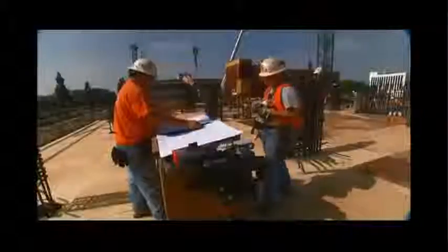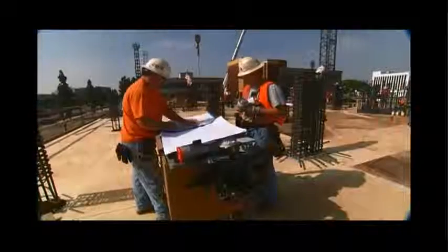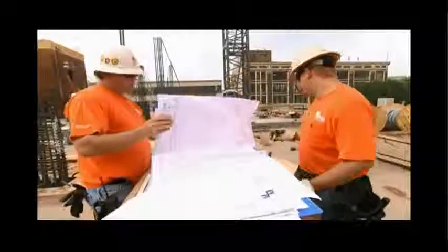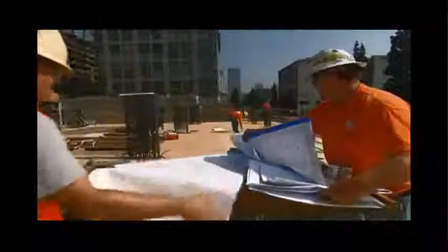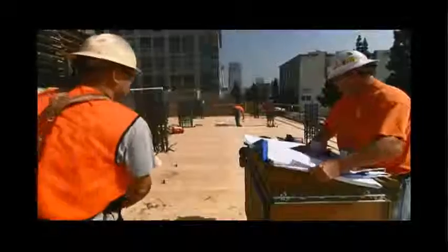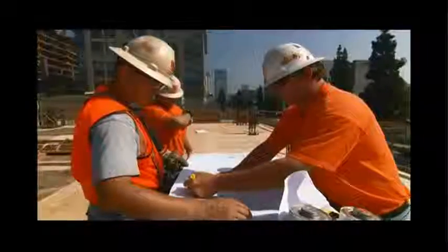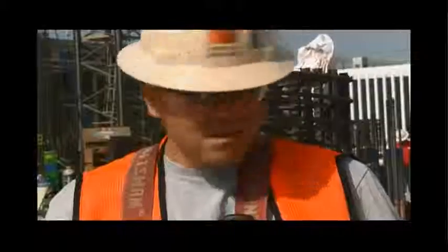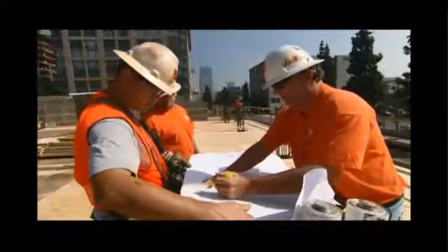Working in the well-equipped shop at BCIT, I am able to implement this instructional strategy by introducing different wiring methods such as non-metallic sheath cable, flexible armored cable, and conductors pulled in conduit, while enforcing the importance of sound mechanical connections, electrical bonding, aesthetic consideration, and functionality. We repeatedly splice electrical conductors using these different wiring methods until the learners are able to successfully pre-assess, install, and test electrical work in a variety of different environments.